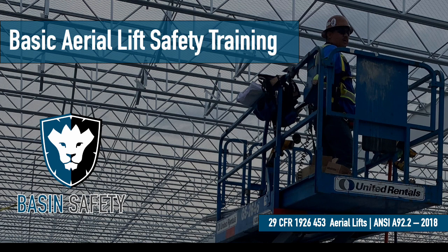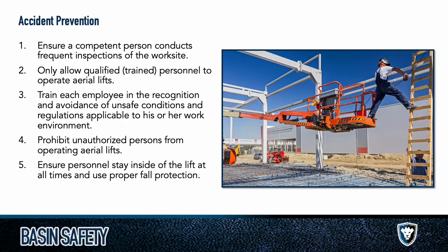So, basic aerial lift safety training. And again, I say basic here because you don't get the card, but we are going to go through some basics of aerial lifts. Accident prevention is pretty much number one when it comes to operating an aerial lift. Unlike a forklift, unless you're operating a scissor lift, these typically have some form of articulation to them, which again, with your center of gravity, same thing, it's going to move with the weight on the equipment.